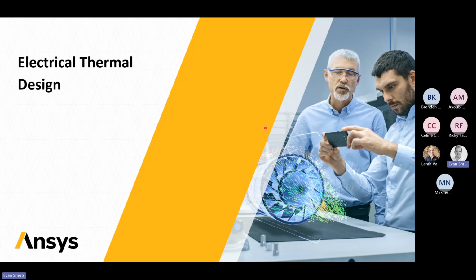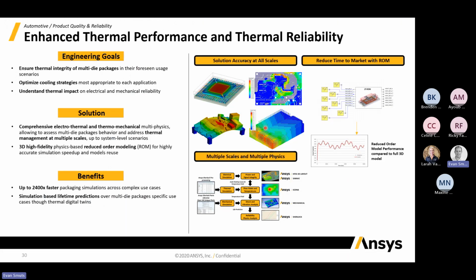Then once we've characterized the electromagnetic performance of the component, we can then start considering the thermal behavior. Okay, so we can actually use the electromagnetic solution, the field model that we've generated, and translate that into a thermal model. So look at ohmic losses in the material, for example, and see where the component is most likely to heat up. Okay, so the idea is that we can start then understanding from our design, where is the heat generated and how can I get rid of it?